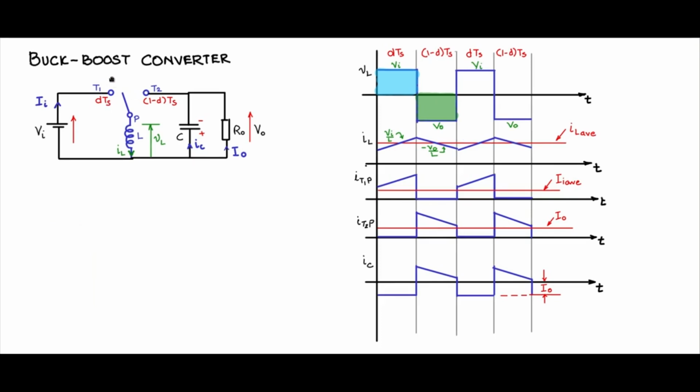Let us now select the switch elements for the single pole double throw switch. Considering the switch elements now, let us find out the static switch requirements, the static characteristic of the switch. Now we will take T1P and T2P one after the other and see how the static characteristic for the switch looks like: V T1P on the x-axis, I T1P on the y-axis.